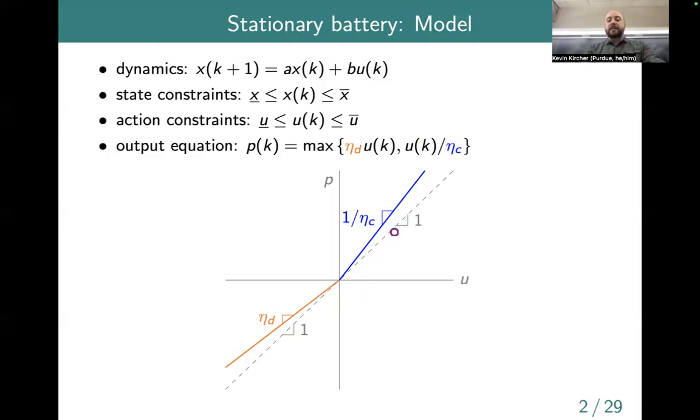But our battery is not perfectly efficient, so we use somewhat more electrical power in order to deliver that unit of charging power. And then conversely, when we're down here, now we're in the discharging regime. If we had a perfectly efficient battery, to do 1 unit of discharging chemical energy, we would get back 1 unit of electrical power. But actually, our battery is not quite that efficient, so we get back somewhat less. And so we get this kind of angled shape here. Questions about this?